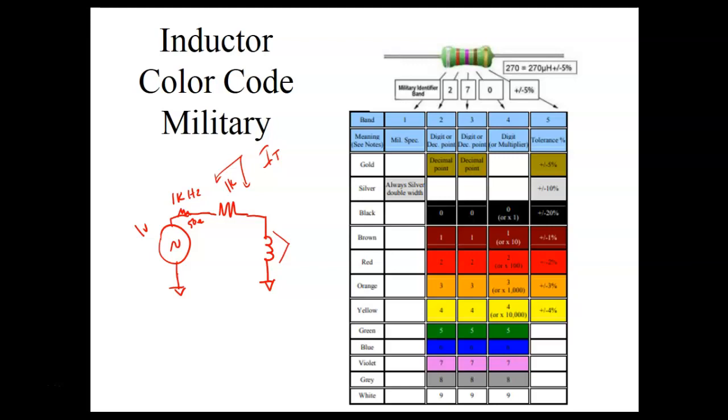Now in a plant, odds are they're all going to be labeled. But most of the time when an electrician wires a house, they don't take the time to label those panel boxes. There's a little tool you can plug into an outlet. If you're trying to turn off an outlet, you plug it in and then it'll tone the breaker. Yeah, you have a little toner that you can run down and it'll beep on the breaker.